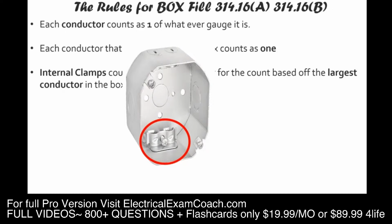What this code is stating is it doesn't matter if I have 1 or 5 of these clamps, we're only going to count it as 1, and it's going to be grouped with whatever the largest conductor is in the box. Meaning if I have 12 and 10-gauge conductors inside that box, this internal clamp would count as 1 10-gauge conductor. All of the fittings we're going to convert over to conductors, then the conductors we're going to convert over to the cubic inches, and you'll know more of what that means as we go through this lesson.